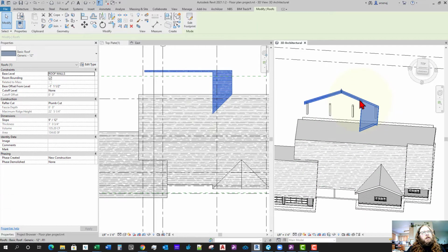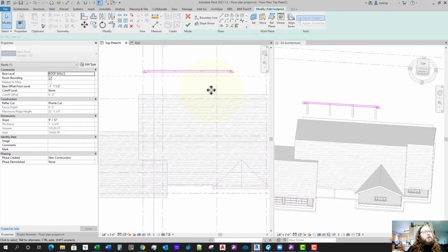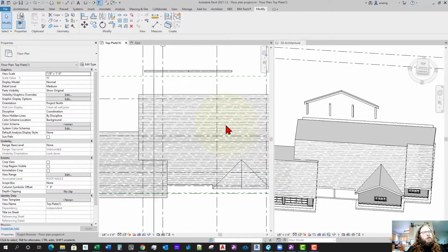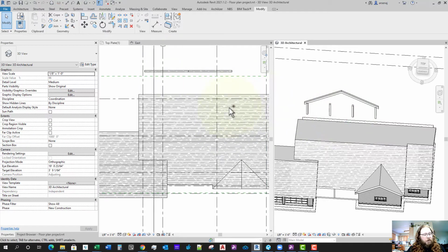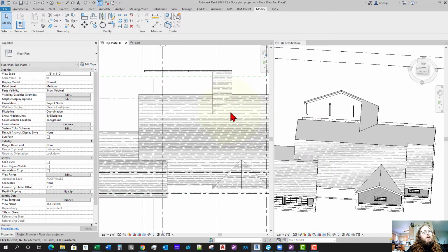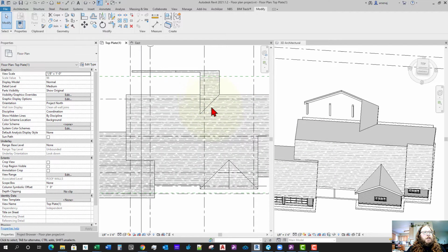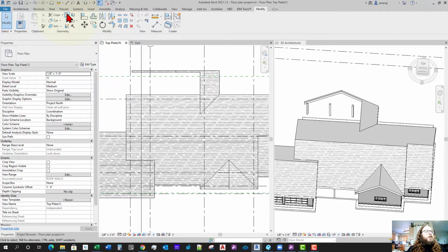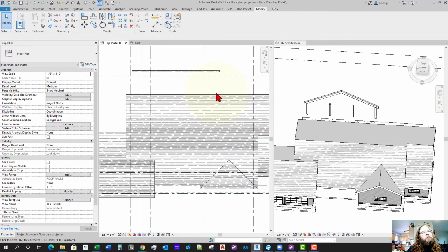And let's see, check out this other roof. So I think this other roof was tried to join, so we're going to try and unjoin it now. So what I did there was, this roof was extended out to here, but the profile was only here. So what I did is to unjoin it, because if you hover over this roof join, it says join unjoin roofs. So if we pick it and it's already joined, we can pick it again to unjoin it.